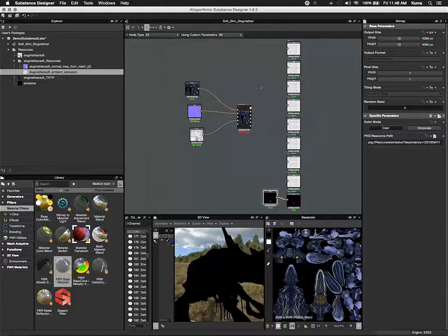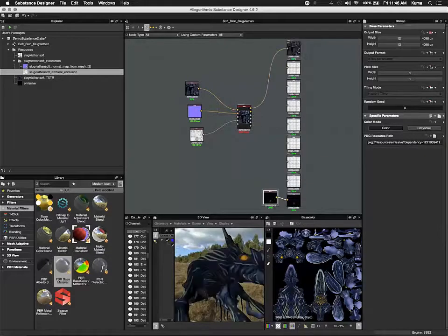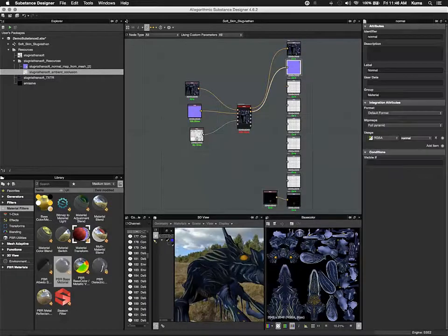Now let's go to the base color from here. Plug it into our output here. Normal. Let's see, I think that was our normal. Yeah, there's our normal. And then let's take our ambient occlusion and drive into the, oh, that's displacement. We do not want it in displacement. Let's delete that. Emissive, ambient occlusion. There we go. All right, and let's connect this back into our emissive.